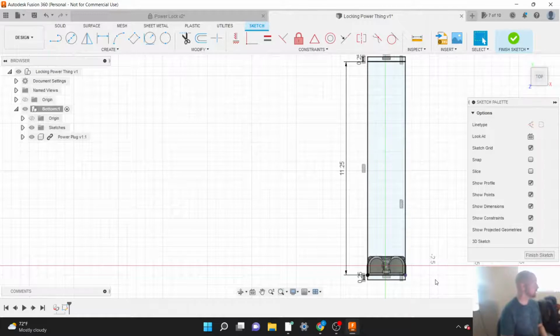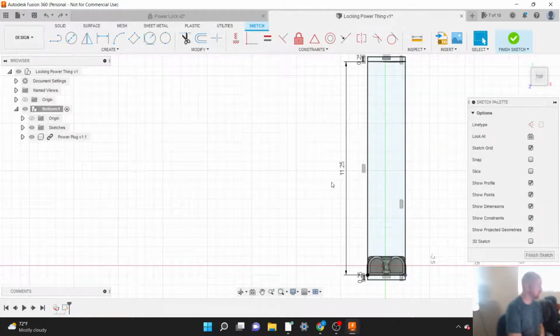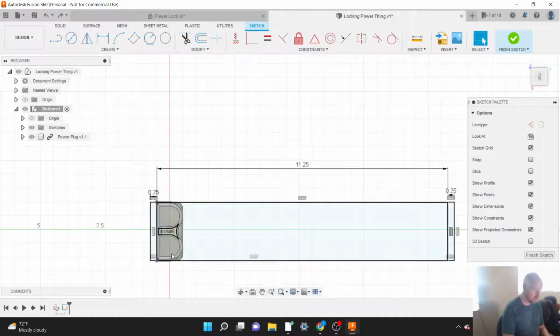Oh, so it'll move with it, all the other parts. Exactly. Yeah. So, it's easy for me to change this measurement to 10 inches, and I know that if everything is fully constrained, it's going to move in a predictable way. Sometimes if you have blue lines along with your black lines, those blue lines are going to move in funny ways because they might be locked in position over here but not in length, or locked in length but not in position. So they don't necessarily behave predictably. Good question, thank you.